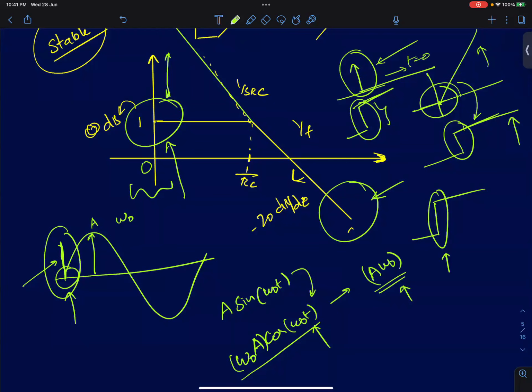So if I throw you a frequency response graph and roughly tell you how the high frequency and DC response look, you can with good accuracy predict the initial or transient behavior of the system and the steady state behavior. So keep this point in mind. We will be using this point to analyze all the circuits. To analyze the transient behavior, you look at the infinite or high frequency behavior, and to predict the steady state behavior, you look at the DC characteristics.